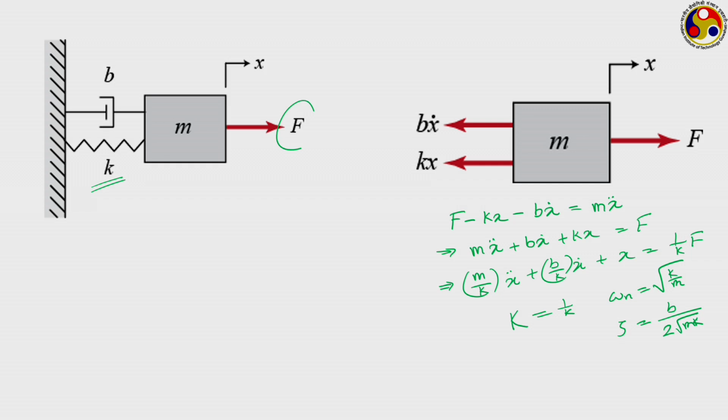If we compare that with the inductor capacitor resistor system that we had, there we had LC d2 Vc dt2 plus, or I should write this, RC dVc dt plus Vc is equal to V in. So, how can we get the expressions? If you compare here, what expressions are you going to get?